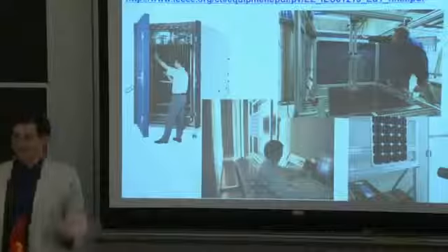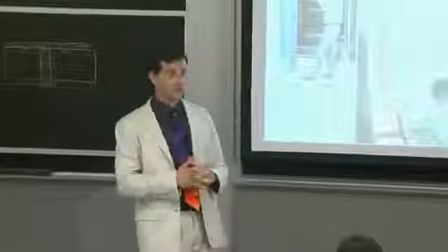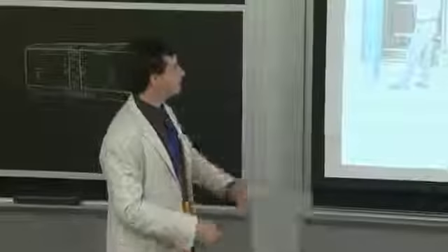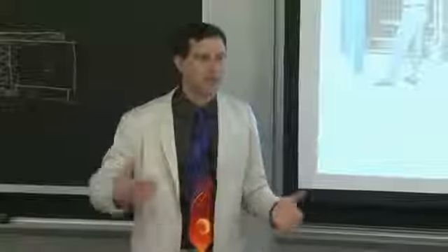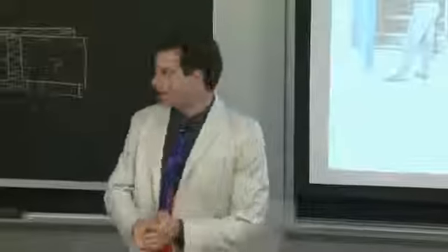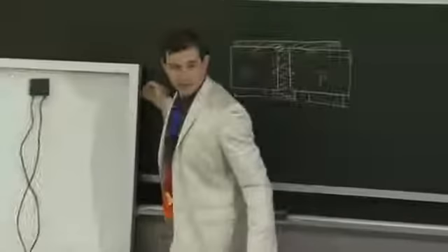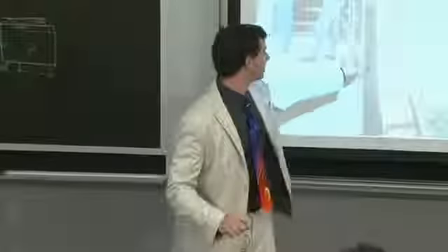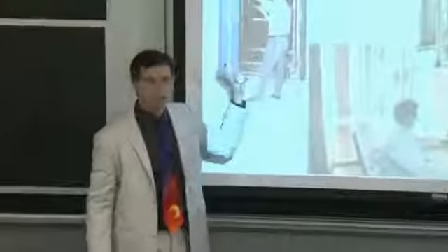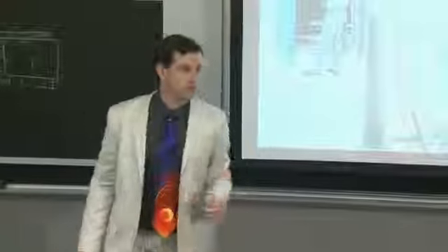So it's not uncommon that you hear about 85-85 tests, which mean 85 degrees Celsius at 85% humidity. Right? So that is a massive jungle. We don't have, thankfully, places on Earth like that. The maximum temperatures are at around 45, 50, 55 degrees C, typically, and in those cases very dry. But in here, 85 degrees Celsius, it's still below the boiling point of water, very high humidity. And the humidity, if there is any place for it to go inside the module, if you have any failure of your encapsulant material, it can get inside, and it'll begin degrading your module. You'll see the power output decrease. And after 3 months, subjected to that sort of torture, if the module is poorly designed, oftentimes it will fail.